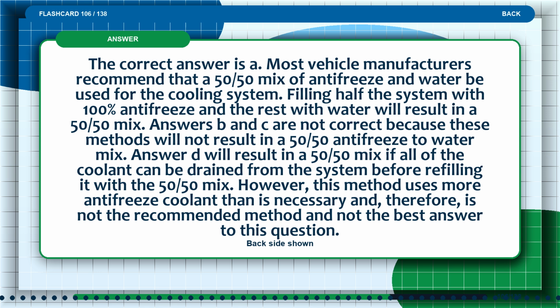Answer D will result in a 50/50 mix if all of the coolant can be drained from the system before refilling it with a 50/50 mix. However, this method uses more antifreeze coolant than is necessary and, therefore, is not the recommended method and not the best answer to this question.